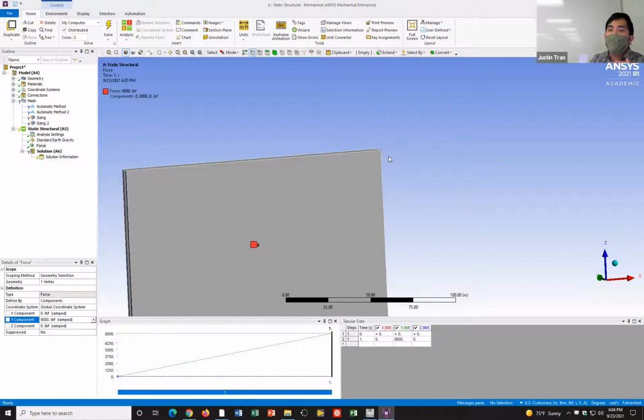Numerically, what's happening is you're going to have a really, really large number in your matrix, and everything else is going to be really, really small. It creates a lot of difficulties because those kinds of systems are called stiff. It's called a stiff linear system, and those are normally really hard. If you distribute the force over a whole surface, then that force gets balanced out between a lot of different nodes, and it makes the linear system a lot more balanced.